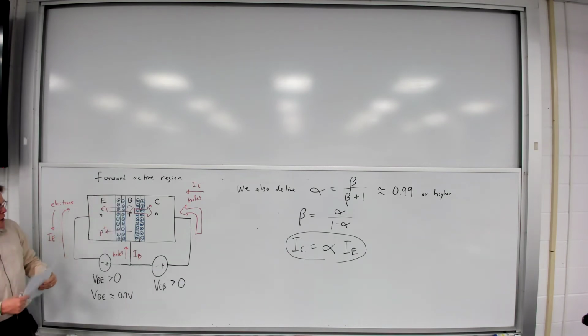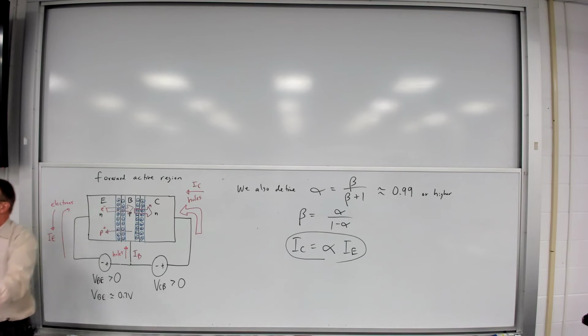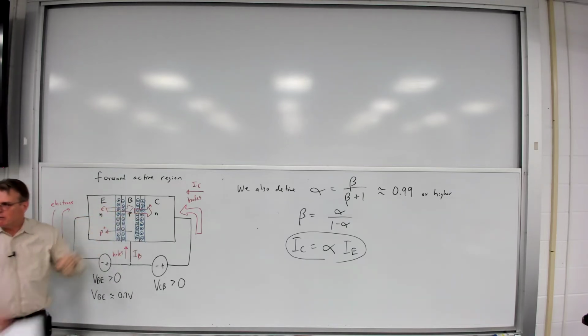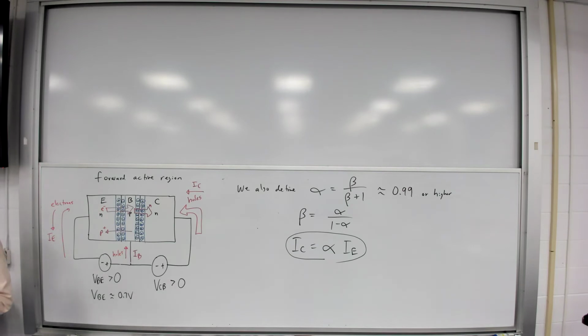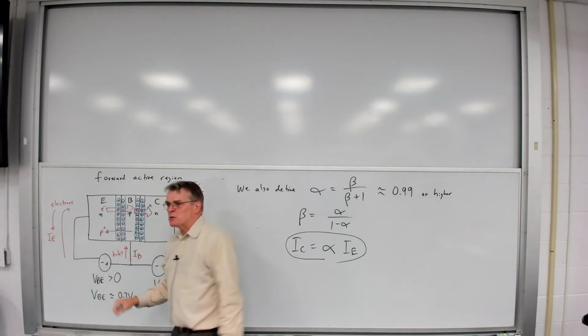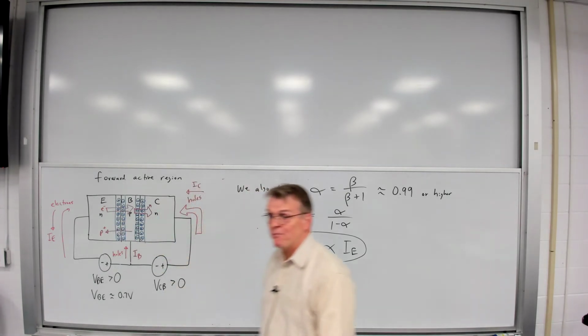But in this case, we are artificially supplying that P region with a ton of excess minority carriers. They're coming from the emitter. Then once they're in the base, as far as this reverse bias junction is concerned, we've got all these excess minority carriers here. They can travel right across a reverse bias junction, and that's exactly what they do. So that's what's going on. And once they realized how this worked, then they could see how they could get current gain out of the structure.